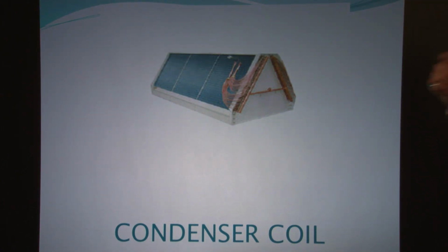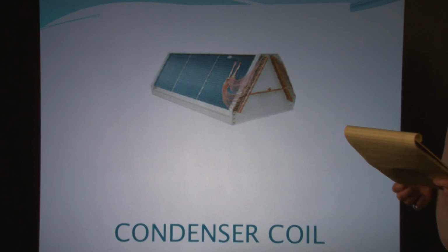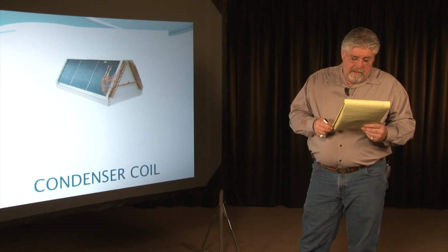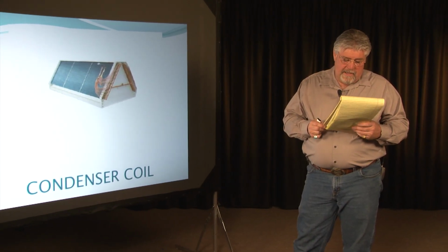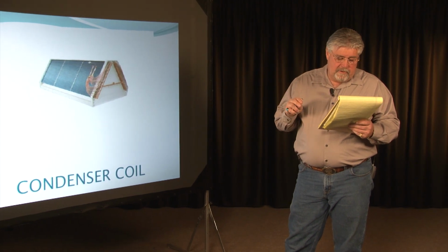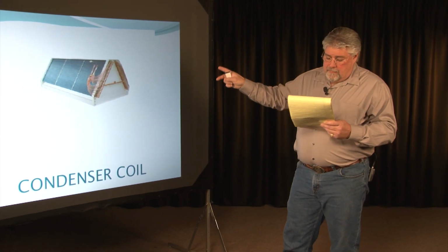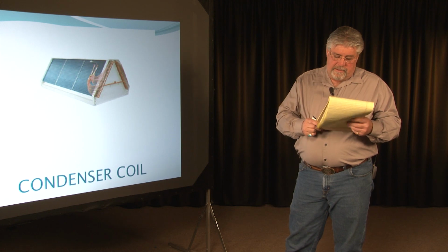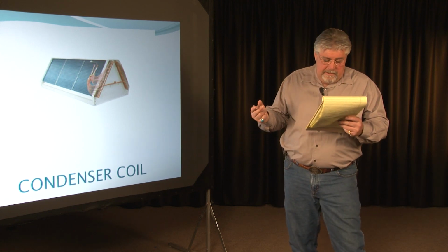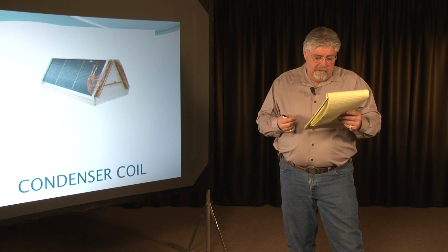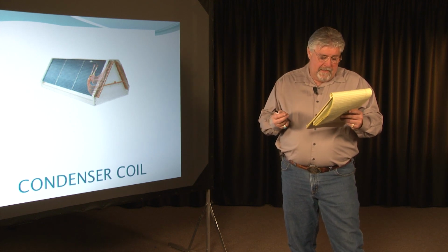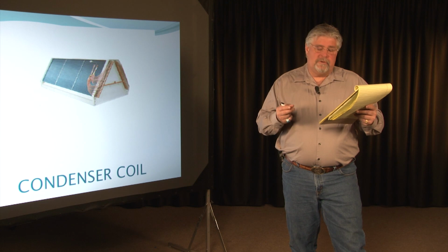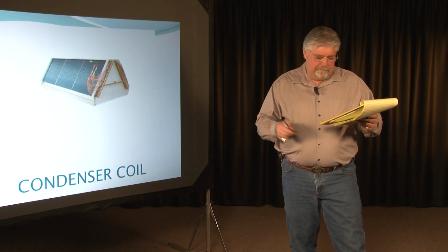Condensing coil. A condenser condenses the gases to liquid by cooling it. When the condenser is running hot, refrigerant gas coming from the compressor enters the condenser coil at the top. And as it passes down through the condenser coil, it cools. Condensers, whether they employ water or air, should ideally eliminate the heat from the refrigerant to change the superheated vapor that is discharged from the compressor and convert this vapor into a saturated liquid, or subcooled is another term.